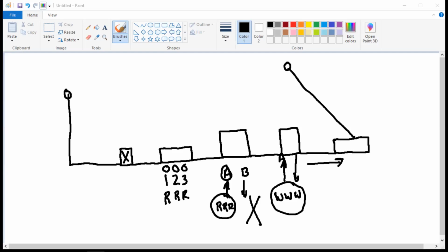I'm good. Okay. So what the fault indicator does, sitting on the conductor, I'll just draw a little window for one. It's got the F in it. What a fault indicator does is it measures the intensity of magnetic field. The only thing that's really inside a fault indicator is a magnet, and it measures magnetic field. And if the magnetic field, because of high intensity load on the conductor, gets too high, it makes that little window trip. So that's how it trips.